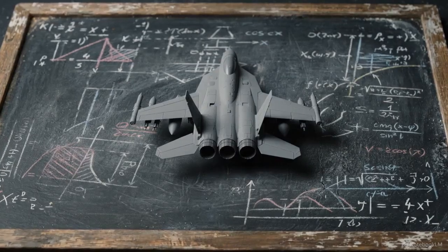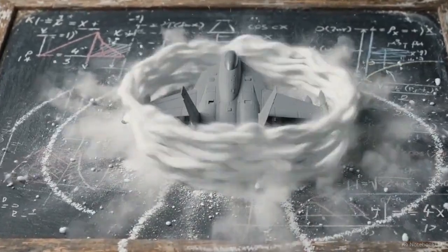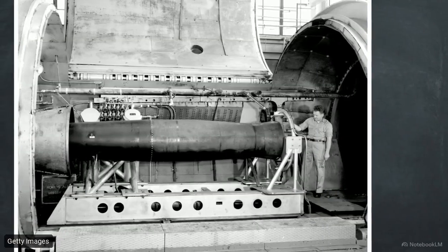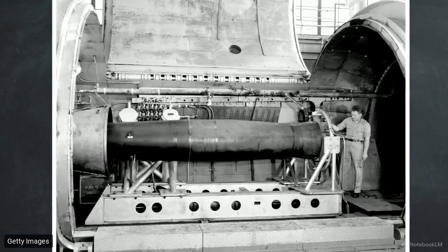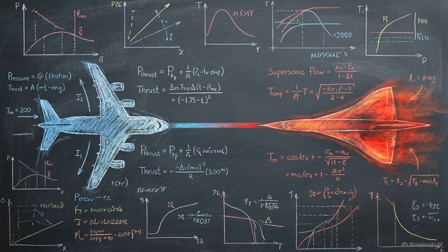Pushing towards supersonic flight speeds requires a different, totally extreme architectural approach: the raw power of the ramjet and the pulsejet. These designs completely eliminate the mechanical compressor and turbine, relying purely on the aircraft's extreme forward velocity to compress incoming air. The architectural choice between a turboprop or a ramjet is dictated entirely by balancing mass flow rate and exhaust velocity against the intended mission speed.